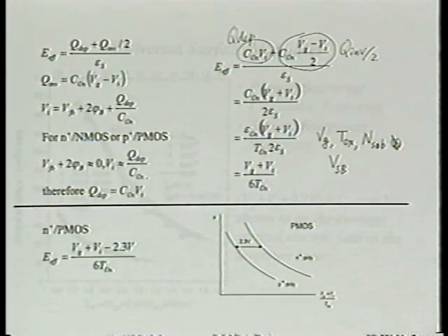And you want to see whether it has changed its mobility. But because these are two different devices, with different implants maybe, VT is always slightly different, and yet he's trying to compare the mobility. For example, maybe he did a retrograde well. He's saying mobility is better. He's trying to see whether the mobility is better or not. But these two devices have slightly different VT.